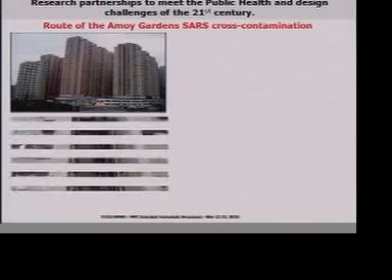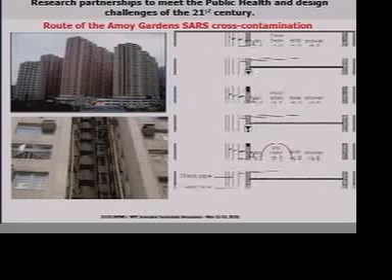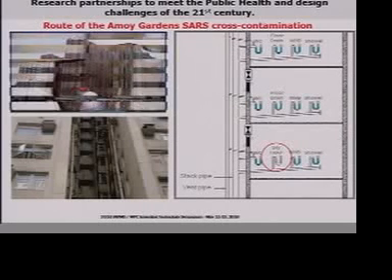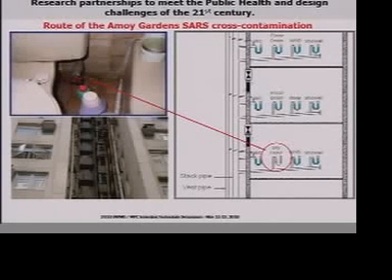The Amoy Gardens building here in Hong Kong has the same sort of external drainage that we saw on the Pac Tin building, and we know that the cause of the contamination was dry traps. That dry trap, in actual fact, not very clear in this, is here just at the skirting board level of the bathroom. Now, with changes in floor cleansing, that trap is not going to get topped up with water because people don't use buckets and mops anymore.